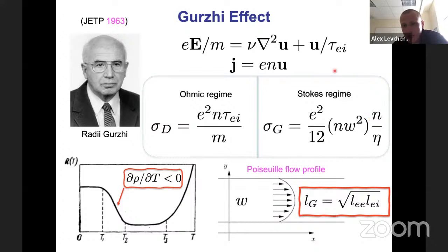Now, to what Ilya was asking me, if you forget about the driving force, meaning the left-hand side of this equation, and just concentrate on the right-hand side, we can see that this combination of the two terms introduces an intrinsic length scale in the problem. So indeed, kinematic viscosity times Laplacian by dimensional units is kinematic viscosity divided by some length scale squared times u.